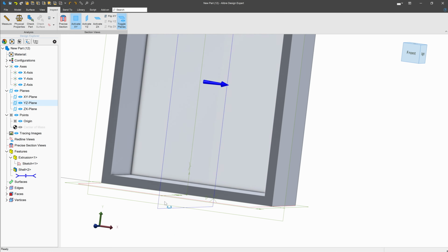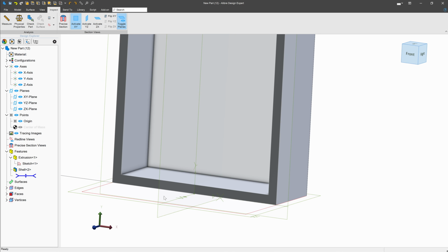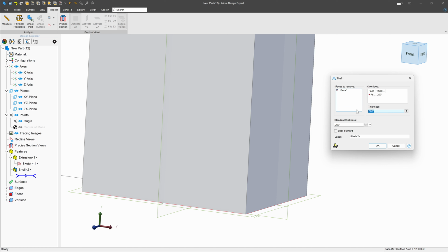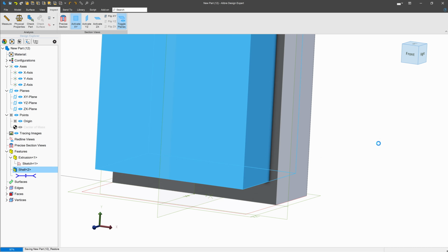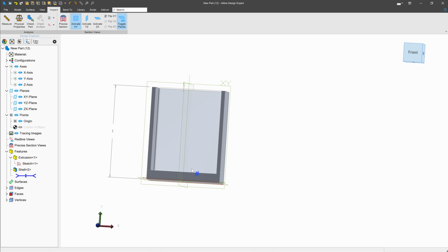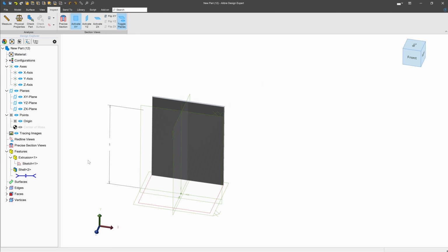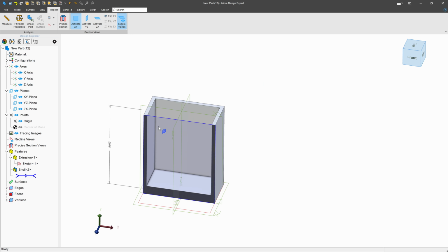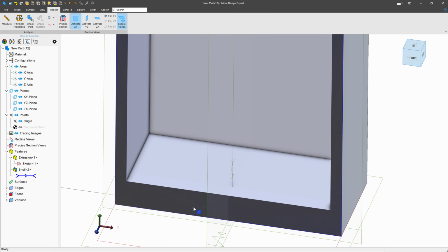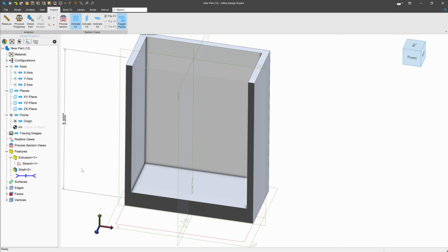As you can tell, we haven't actually applied a thickness. It's pretty consistent all the way through. So we're going to apply our overriding thickness, right? I'm going to say 0.5. Let me actually highlight this face, 0.5. There we go. Now that this says 0.5, we have a thicker bottom face. So we can not just shell, but shell to varying thicknesses as well. I can click this face and drag it too, so I wasn't quite viewing my cross-section there. But there we have our various thickness.